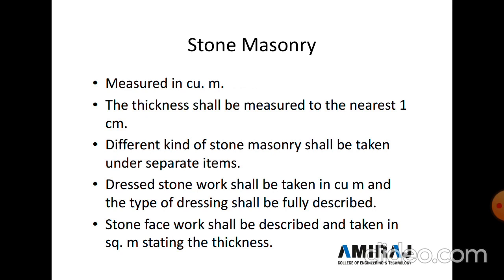Dressed stone work in sill, lintel, step, column, coping, etc., shall be taken in cubic meters, and the type of dressing shall be fully described. Stone face work shall be described and taken in square meters, stating the thickness.